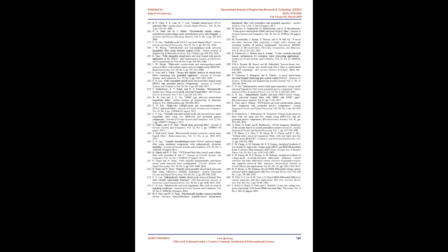Conclusions. Only using 3 single-output DDCCs, 2 grounded capacitors, 3 grounded resistors, and 1 floating resistor, a general mixed-mode universal biquad filter is presented in this paper. Filters using active elements with simple implementation configuration, such as single-output DDCCs, have the advantages of the lowest cost, power dissipation, chip area, and noise. Filters using single-output active elements, such as single-output DDCCs, have the advantage of no need of extra current replicas degrading the final output impedance.